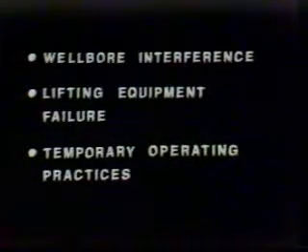We will now discuss a few of the practical realities of plotting production data in order to obtain accurate decline curves. We may divide our discussion into three principal areas. First, how we distinguish changes in the production response of the reservoir from changes in wellbore conditions or operating practices. Second, how production data is prepared for extrapolation. And third, how we incorporate changes in operating practices, for example, the addition of a new well to production or the installation of artificial lift, into our decline curve analysis. Let's begin with the first area.